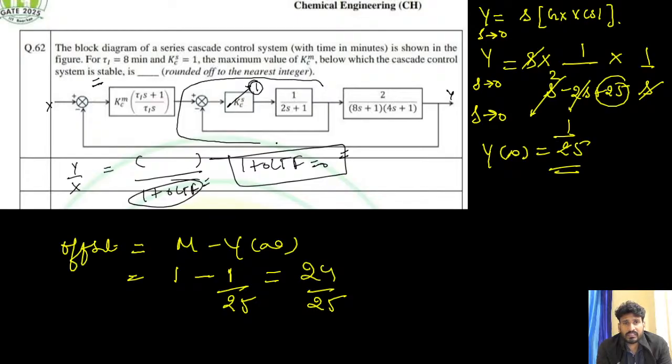Are we able to calculate the transfer function of this branch? Yes sir. Let's suppose it is X. Right now, this is the problem of the stability. Okay, we can calculate this question with the help of Routh array. Yes, Routh table, from Routh array we can do this. For Routh array, what is the first requirement? Characteristic equation. What is the characteristic equation? The transfer function denominator equation.